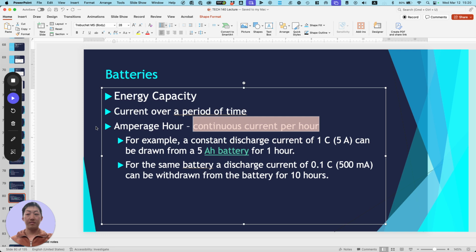But generally, the power is going to flow through the ESC first because that's the most power-hungry thing, and then it gets redistributed later. But it could also go straight to the flight control board if it's perhaps a smaller battery. But the battery we're dealing with here has too high a voltage, so it can't go straight to the flight control board. It has to get stepped down through the ESC as well. And then this is where the power and signal and all that stuff goes through.